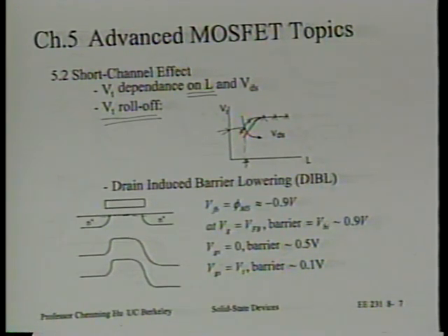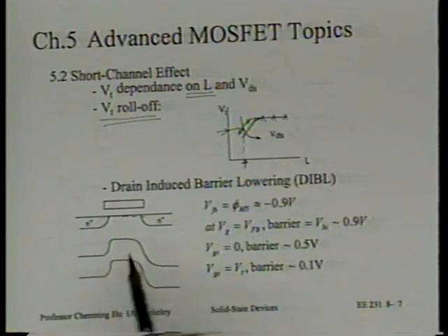But if you're dealing with a high-speed transistor, VT is lower for whatever reason, you have 10 nanoamp leakage at VG equal to 0. What is the barrier height? Whatever corresponds to 10 to the 15th electron concentration, right? Which happens to be about 0.3 eV. So that's the kind of barrier we're talking about when VG equal to 0. Is that right? Okay?